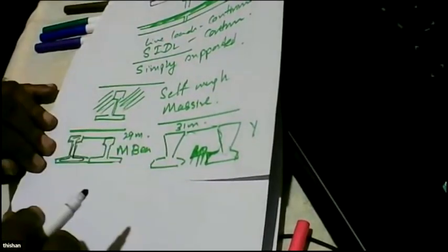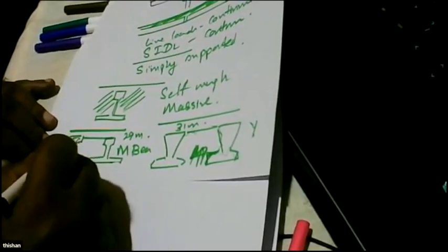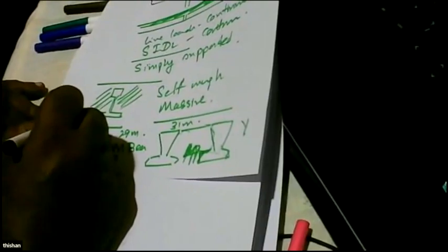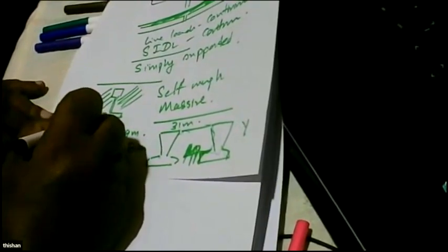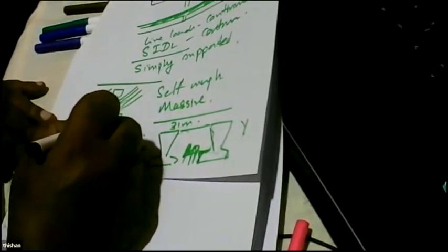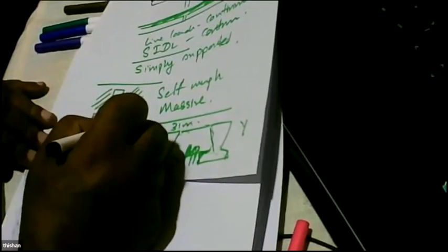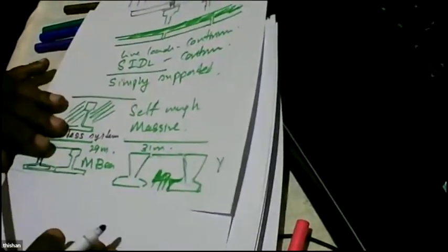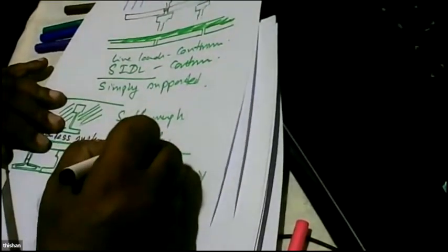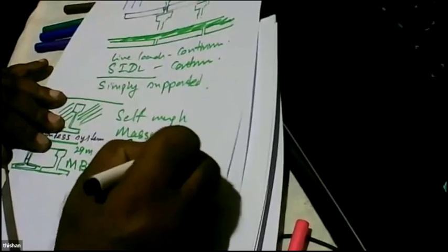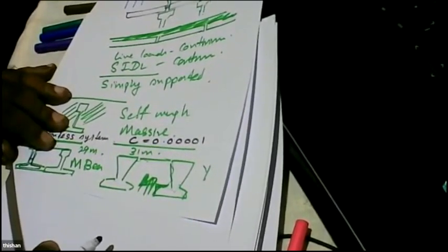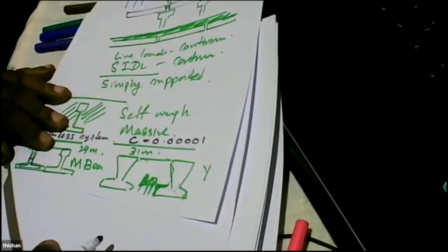So this lever arm is very small. It has no capacity. So then they said, let's analyze this as a torsionless system, which means the torsional constant values are considered very, very small in the grillage analysis. The torsional stiffness values are made extremely small in the grillage analysis.